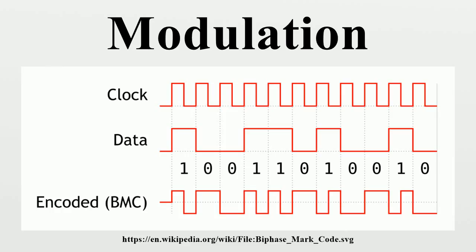In the case of PSK, ASK or QAM, where the carrier frequency of the modulated signal is constant, the modulation alphabet is often conveniently represented on a constellation diagram, showing the amplitude of the I signal on the x-axis, and the amplitude of the Q signal on the y-axis, for each symbol.